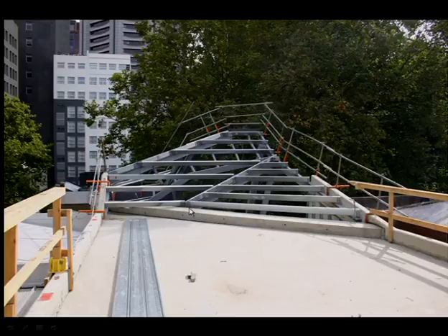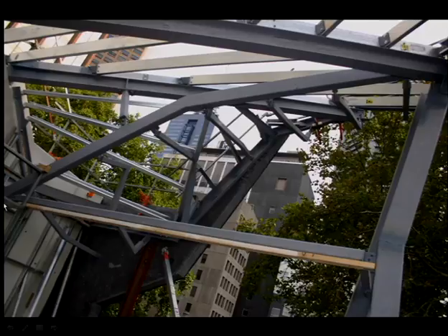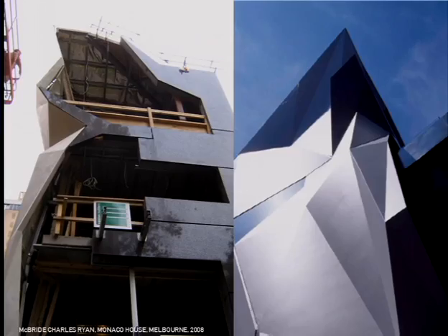And here you see the primary beams, and then you see the girts or the purlins. So you see again primary members and secondary members, that they're ready to get the cladding panels onto that. And unfortunately, I don't have photos of the stage in the middle, but you see these panels are actually attached to that skeleton. And the way you define the spacing between that is according to the size of the panels.